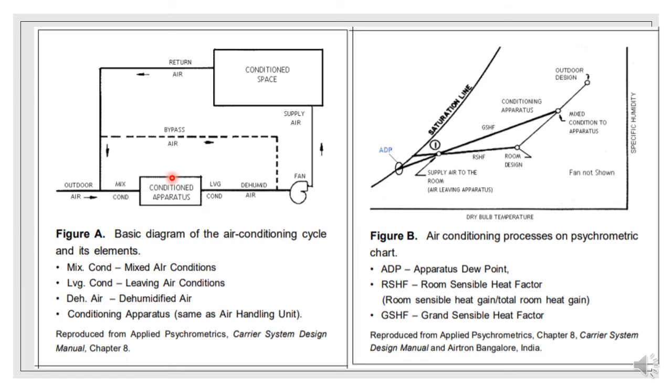The cooling coil is a heat exchanger, and today it is typically copper tubes and aluminum fins, and typically a refrigerant or brine or maybe water flows within the tubes, while airflow is outside and through the fins.